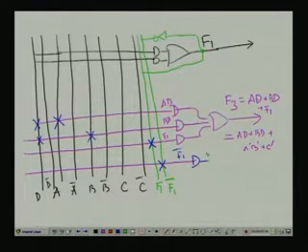So, here one advantage we have seen, or one special type of PAL structure, where the output of the fixed OR plane is again fed to the input of the programmable AND plane, and in that way it extends or increases the programmability as well as the design variety of the PLDs.